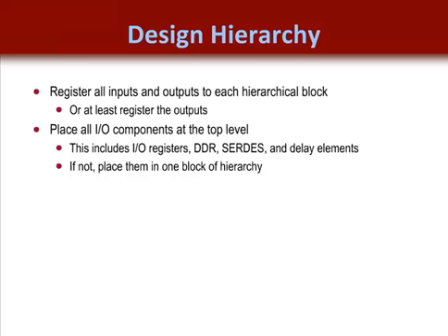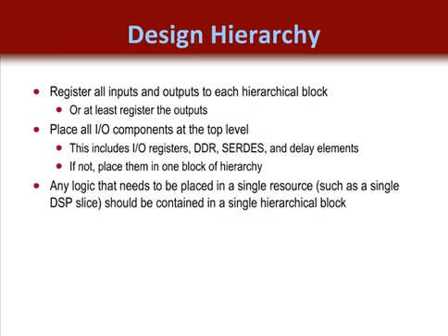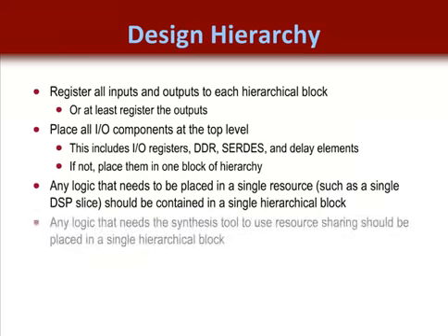While inferring I/O registers is usually okay, instantiation of double data rate registers or DDR, SerDes resources, and delay resources is recommended. It's just plain easier than inferring those resources. Also keep in mind that any logic that needs to be placed in a single resource, such as a block RAM or a DSP slice, should be contained in a single hierarchical block. Any logic that needs a synthesis tool to resource share should be placed in a single hierarchical block as well.